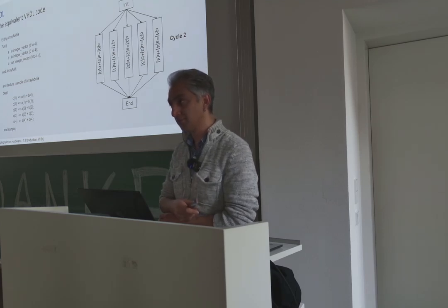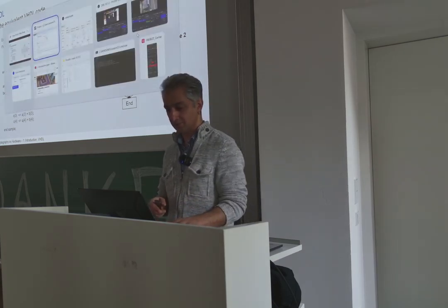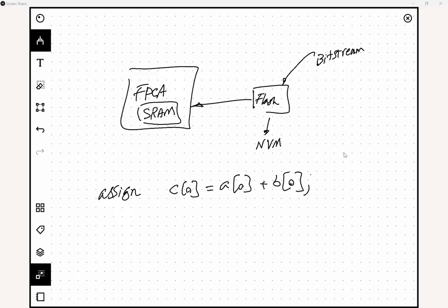The assign that I wrote is not a blocking assign like in Verilog. Blocking and non-blocking things are just in the process, not if you just write assign. I mean, you probably mean this one, which is not here. This is just in the always statement in Verilog. In VHDL, this is something that is called process that we will learn later. But for assign, because there is no process, there is no blocking or non-blocking, because there is no clock.